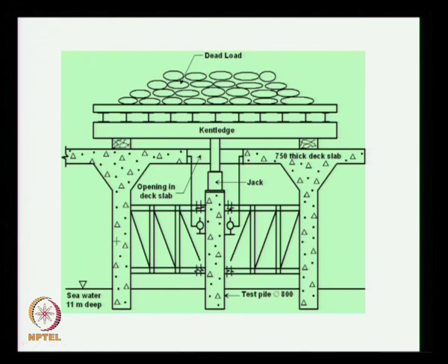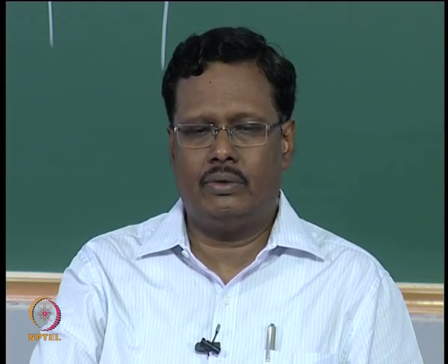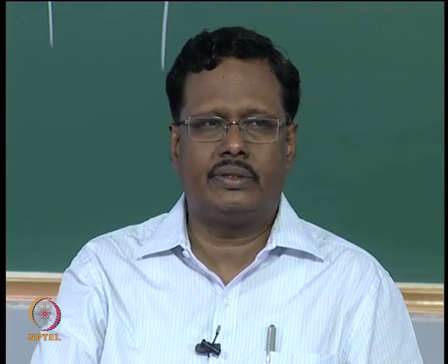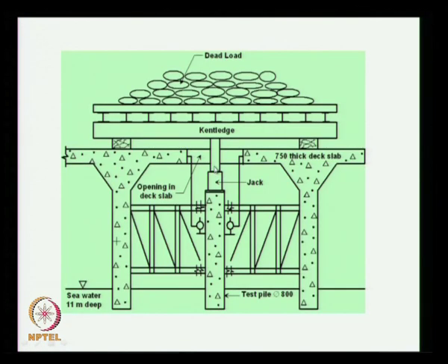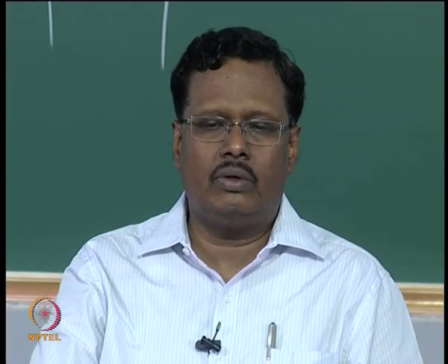Where will the load go? Yeah, it will go to the 4 corner piles. Then what you do is you apply the jack, then the piston will go and touch it, then you apply 100 tons. This total weight is 1000 tons, you apply 100 tons here. What will be the load coming onto this? 100 tons. What will be the load going onto the 4 corners?